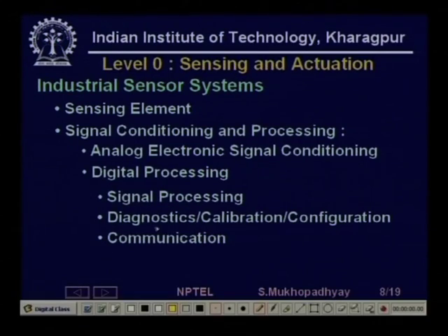Fine. So that is diagnostics. Sometimes sensor characteristics degrade. For example, suppose a sensor develops a bias, you can have algorithms to actually detect the bias, and you can do its own calibration. A sensor can send information that it has developed a bias, or the sensor can be interrogated, and you can find information that it has developed a bias. So, its readings will be interpreted accordingly for greater accuracy, or it can do its own configuration management.